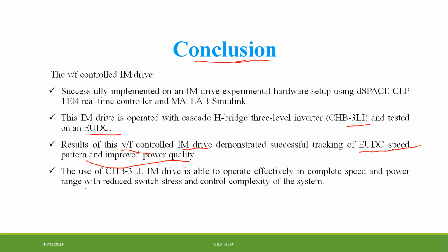The use of the CHB 3-level inverter induction motor drive is able to operate effectively in the complete speed and power range and reduces switch stress and control complexity of the system.